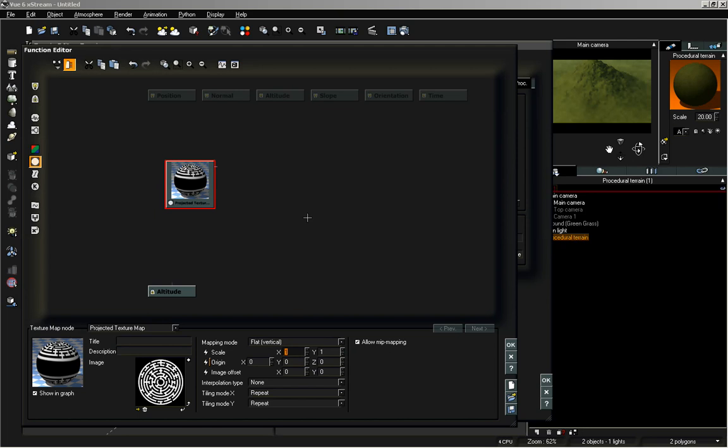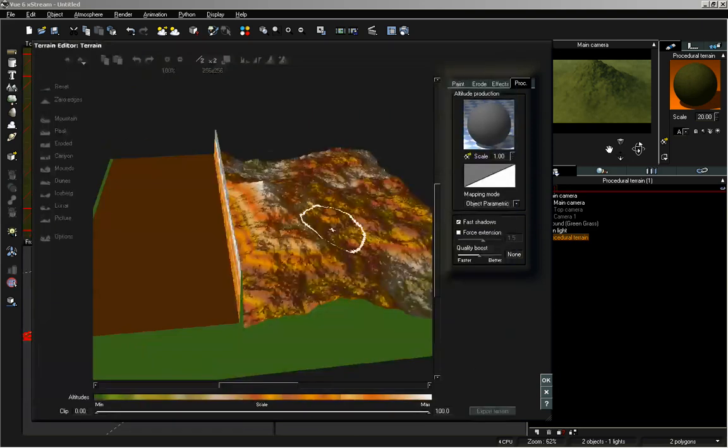And because we're going to be using some modifications and different filters and nodes to adjust the way this looks, I'm going to scale down our object a little and our overall image. Let's go ahead and bring that down to 0.7. And then our tiling mode, which is going to repeat after it reaches the end, I want to make sure that I turn that to none, and that way we just have that one image showing up. You can click OK.